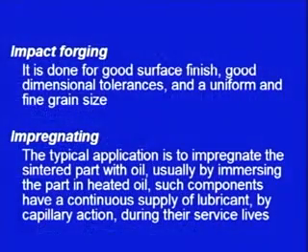The third important secondary operation is impregnating. Impregnating basically is to impregnate the sintered part with oil, usually by immersing the part in heated oil. Such components have a continuous supply of lubricant by capillary action during their service life. Basically if we want to make self-lubricating bearings which will supply the lubricant during their operation, then we will go for the process of impregnation.